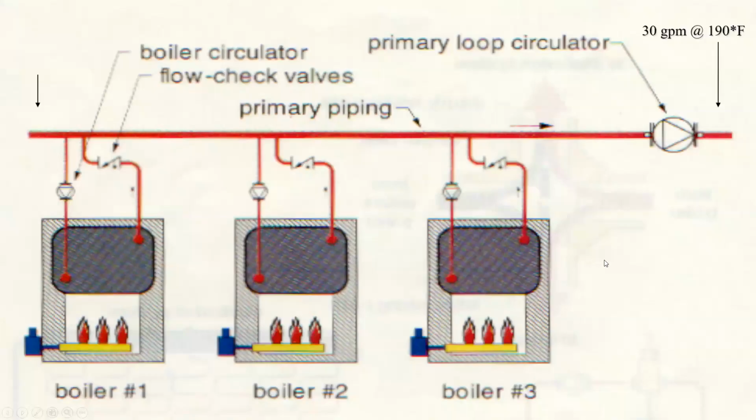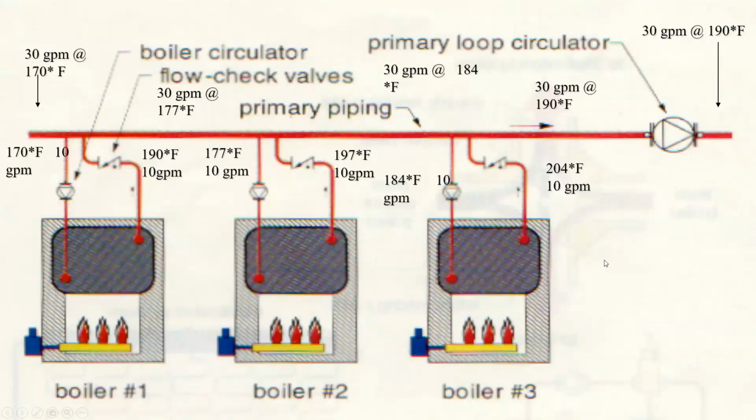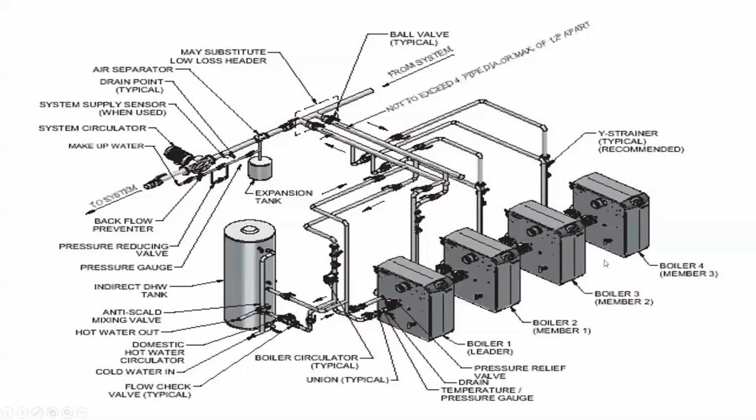And that's that one pipe versus a two pipe. If you look in some of the other boiler manufacturers, this would be like out of, say, Lochinvar's manual. What's the difference here? If I have my return and here's my supply, say that was my 30 gallons a minute, I'm connected with closely spaced T's, but it's almost like a two pipe because I've created this manifold in each boiler. What has its own pump, right?